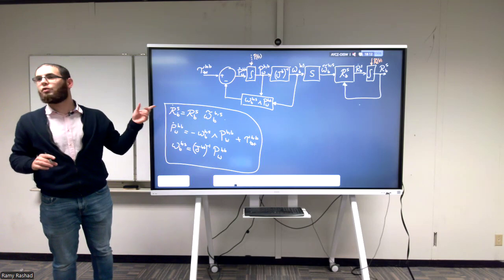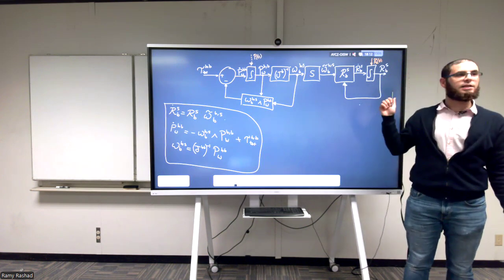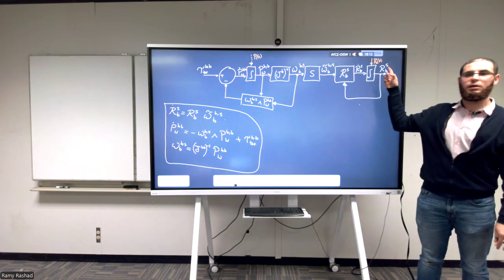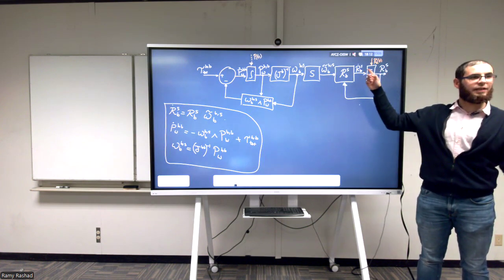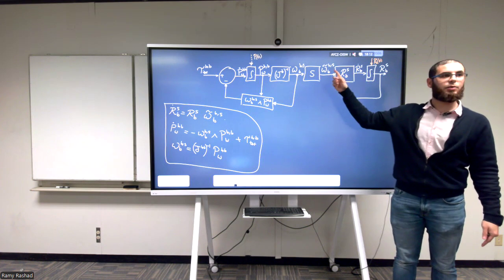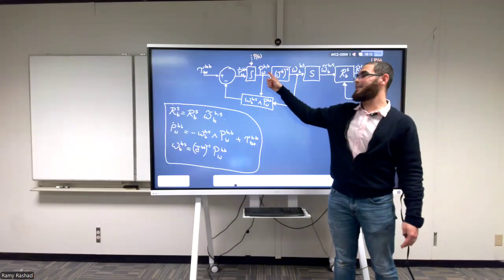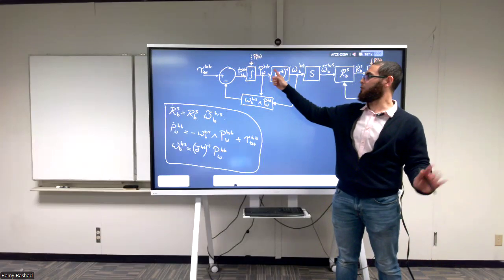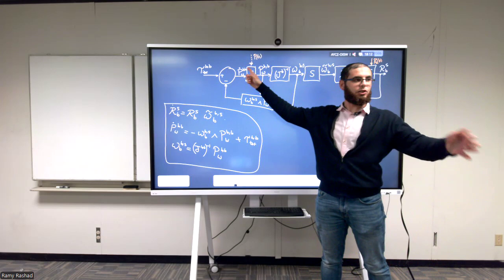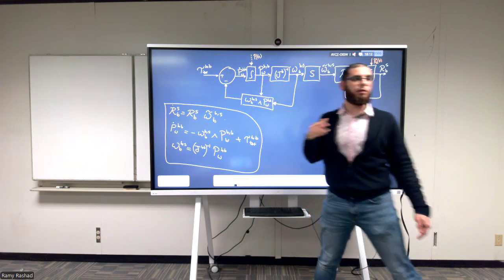Okay. Try to do it with Euler angles. You're gonna regret your life. It's not as beautiful as this. Because simply, now we can talk about the spaces, right? This is an element of SO3. This is a tangent space, element of the tangent space. So it's a vector in the tangent space. This is an element of the algebra. This is an R3 vector that's just isomorphic to that element. This is a covector, properly speaking, without saying what that is now. And this is the rate of change of that covector, or an element of the dual algebra. And then torques, and simply this is just the dynamic part.